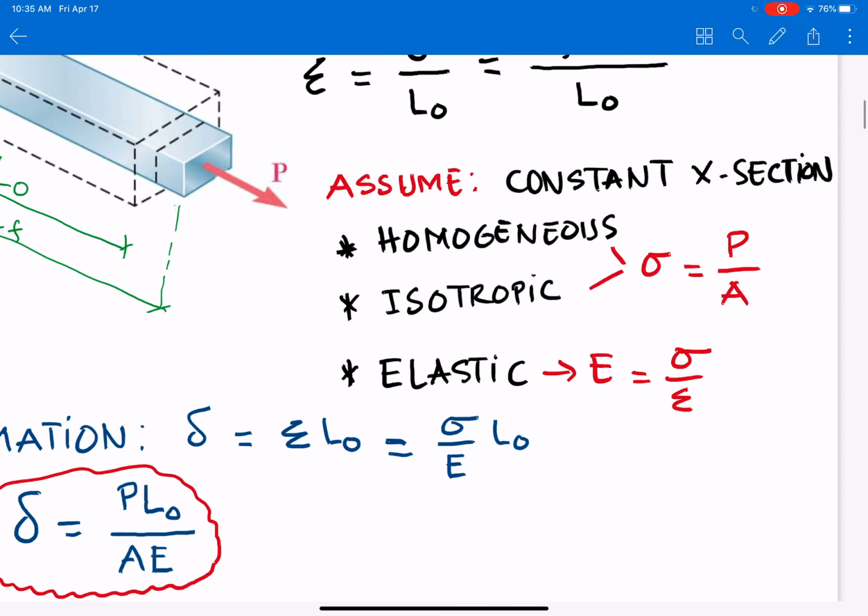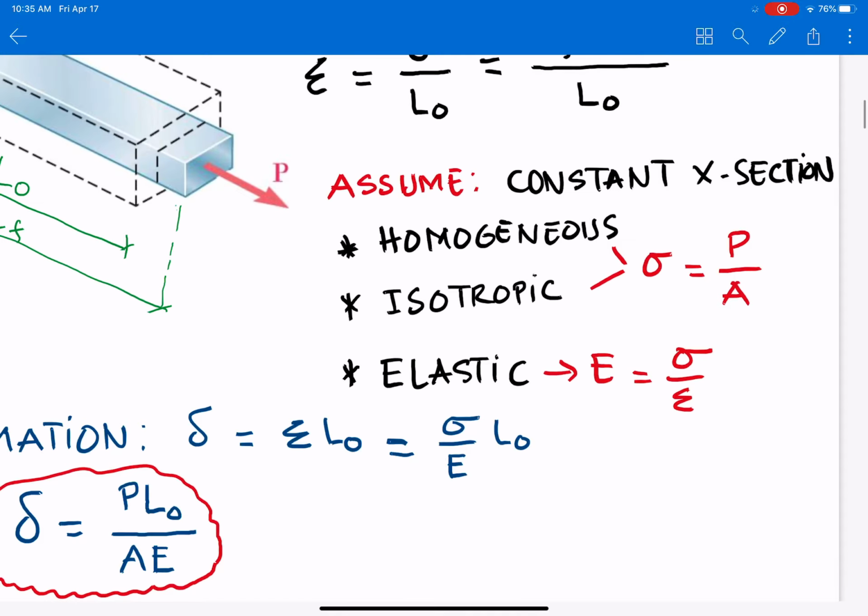First, it has to be homogeneous. That's good because that is still isotropic. So we have sigma equal to P over A, good. Because that's steel and aluminum, it holds for those two. Cross section, constant. Cross section, yes. Aluminum 2 inches square. No, aluminum is 8 inches square and steel is 2 inches square. So the first three assumptions are correct.